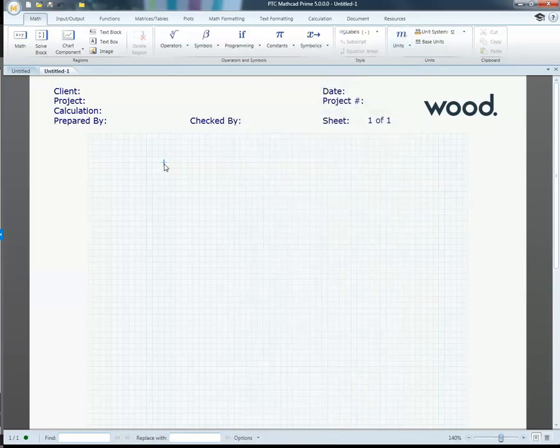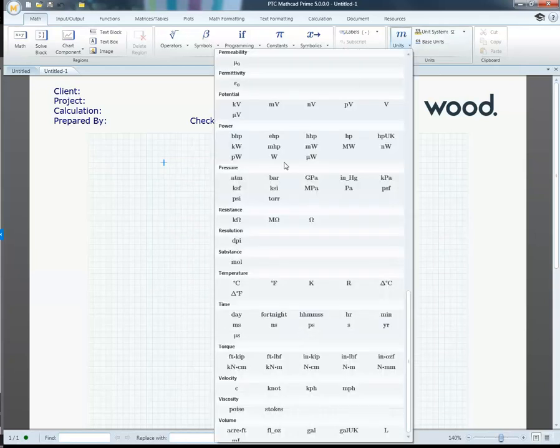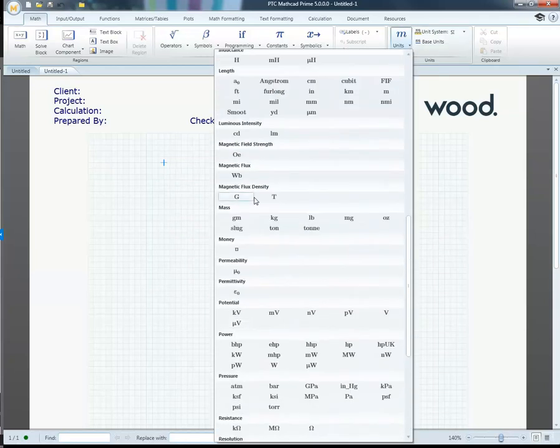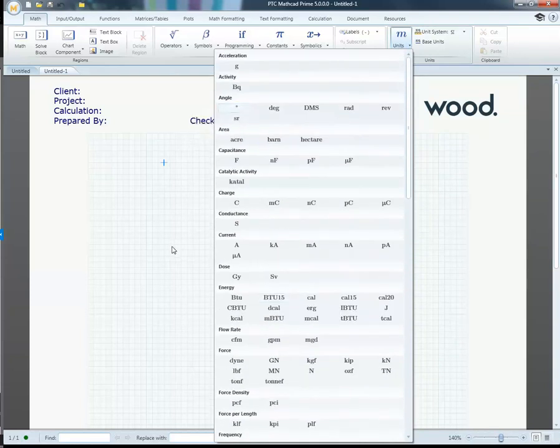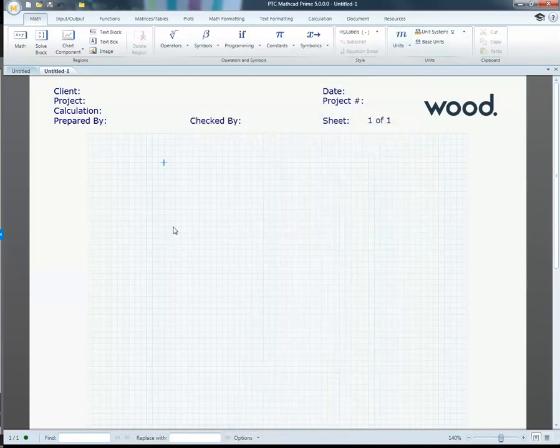So a workaround is that if I wanted to type in 25 degrees, I could type in DEG and hit equals, and then that converts it to radians, or I can put RAD and it makes it explicit. So you can convert from degrees to radians, but I still like the little degree symbol because I think it looks nicer in a Mathcad format.